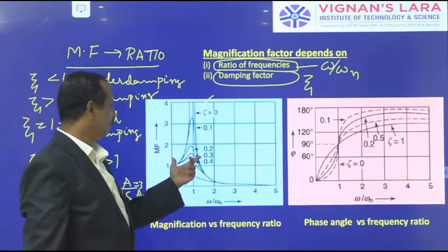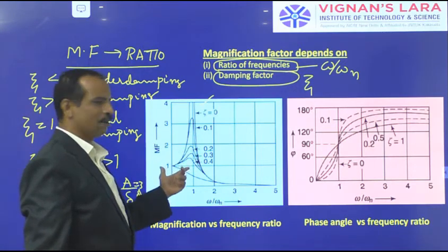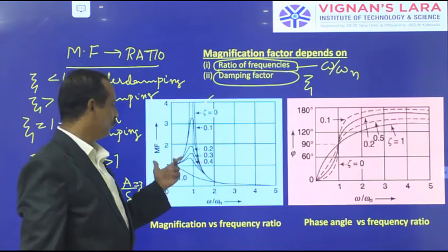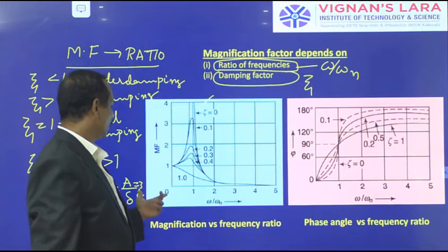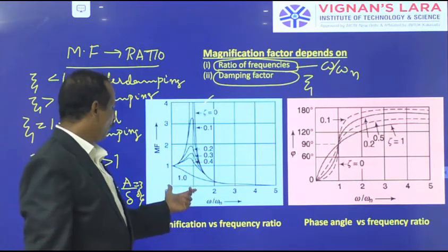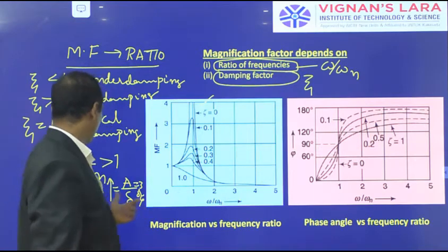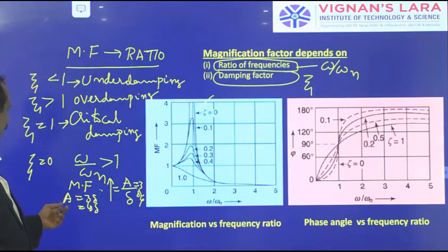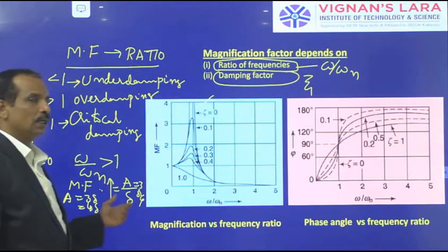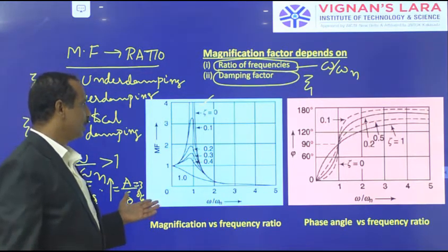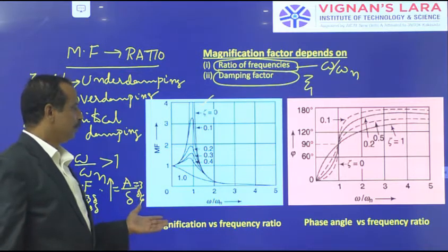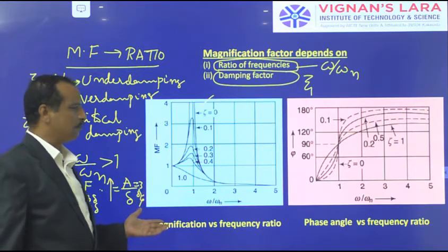That means if you provide very little damping, or no damping, then the vibration will have a large effect on the displacements. The amplitude may be 3 or 4 times the static deflection, so the body will undergo vibration with a large amplitude.